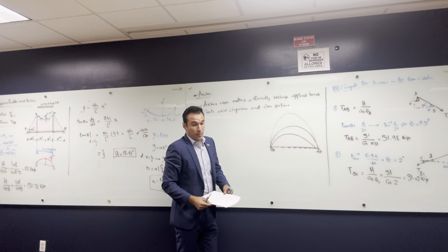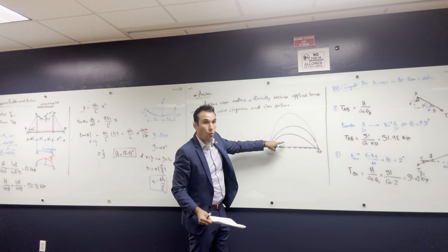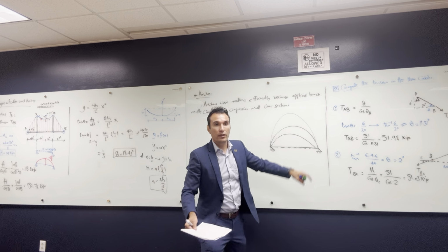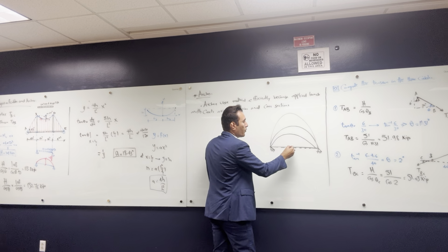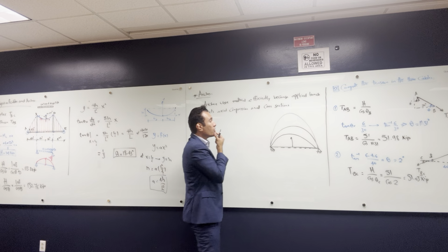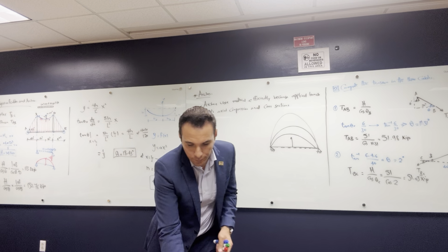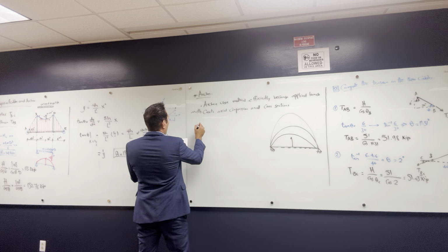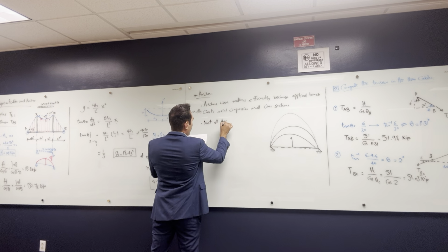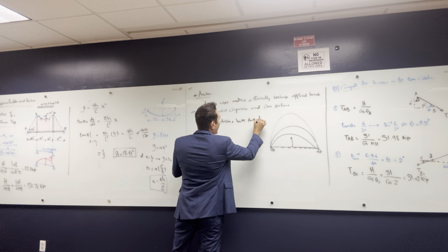All right, if you go down, this arch is tending to be a beam, right? Once we go down, at some point it's gonna be a beam and take full bending moment. But once we go up, this arch is going up, there is gonna be less bending moment, okay? So we wanna find out the arch, let's call it that way. Not all arches have pure axial loads.